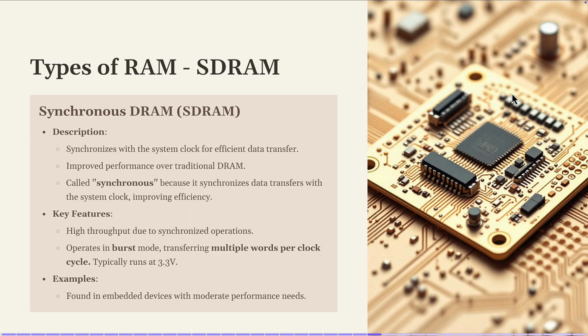Okay, so the DRAM has made several improvements over time. The SDRAM, which is synchronous, here instead of sending bit by bit, it will collect them in what we call multiple words and send them in batches, in bursts. So this will improve the efficiency, because it will be synchronous and synchronizes the data transfer with the system clock instead of sending every bit together.